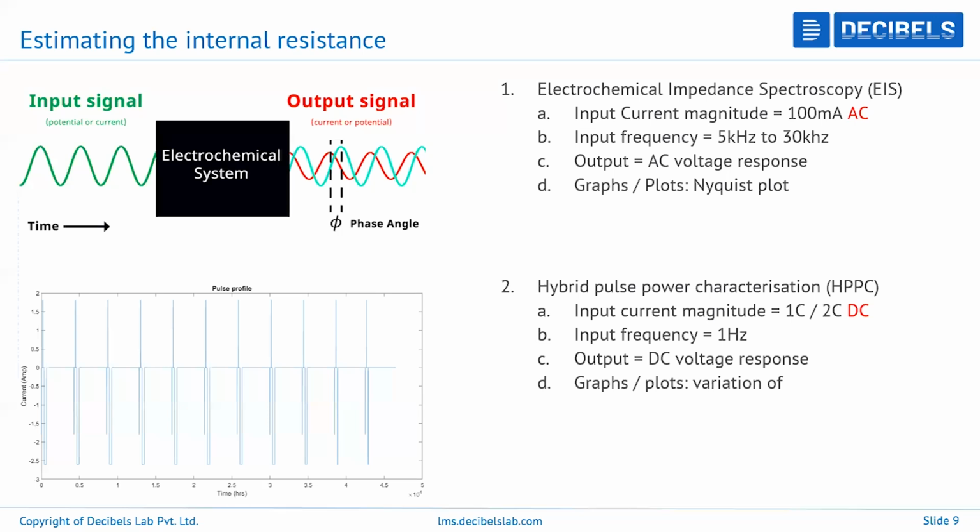The poll asks whether open circuit voltage is sensitive to ambient temperature. I see that many of them have selected that it is indeed sensitive. The truth is, yes, it is sensitive. We have to consider the variation of the open circuit voltage with respect to temperature as well, because the reactions inside once again affect the voltage response on the outside. So it is very important, we have to consider it, and yes, open circuit voltage is very much sensitive. I see that the majority, 71%, have selected that. So good to know that the audience is on track.